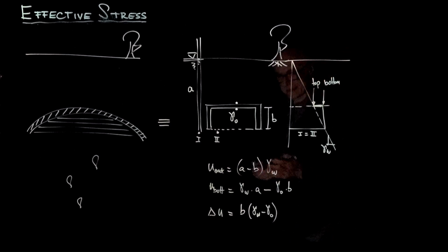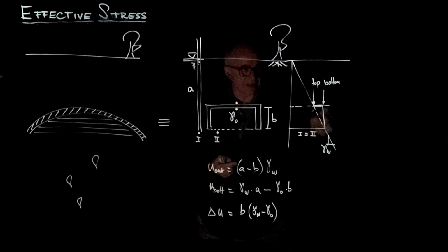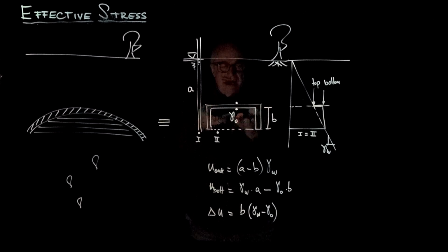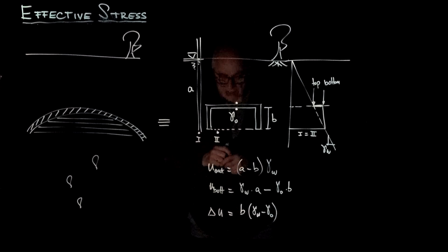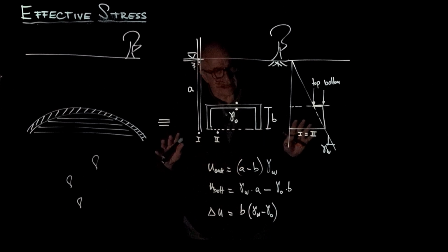Finally, this buoyancy, because of this higher pore pressure from inside, is pushing this bucket up. Therefore, the effective stress in the sediment below the liner will be lower, similar to what we saw before with the aquitard. Now, what is the horizontal effective stress in this case?